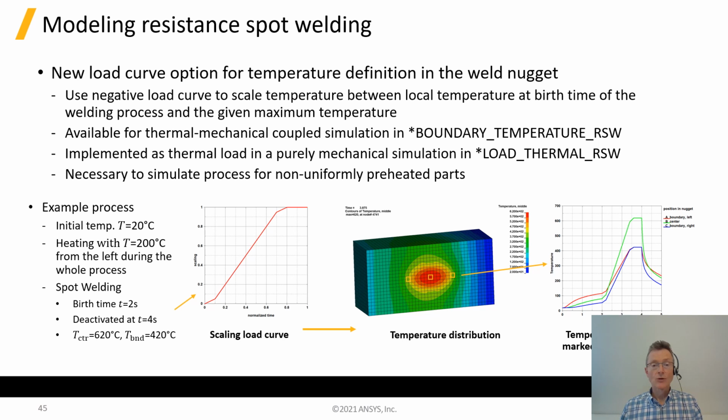There's a feature for modelling resistance spot welding, where the temperature history of a central ellipsoid region is defined, and then the thermal analysis works out the temperature histories in the surrounding region, and that will all become the heat affected zone. The idea is to couple this with material models that change their structural properties according to previous temperature history. This feature has been enhanced in R13 to enable you to prescribe the temperature in the final stages of the heating via a load curve.